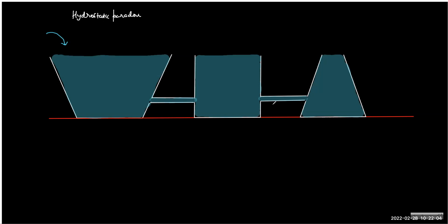The reason is simple. The flow occurs due to the difference of pressure. So water will flow till the pressure becomes equal. Now for the pressure to be equal, the only thing required is the level, like what is the depth of the point from the free surface, and you can see every free surface is the same.